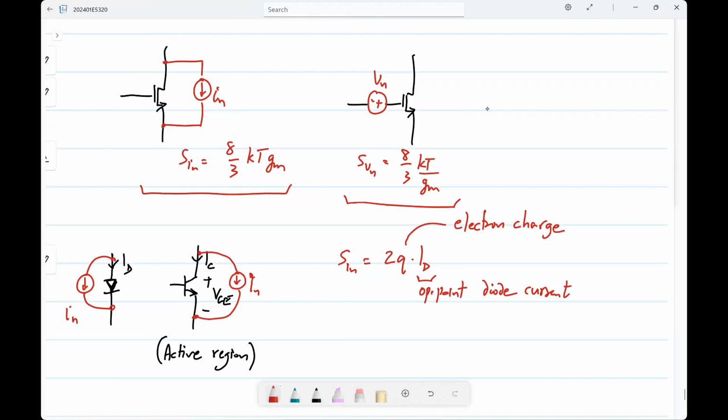In the small signal model of the MOS transistor, we have the current source going from drain to source, the drain current in the same direction, but it doesn't matter if you had put it the other way. The only thing is, in a single calculation, you don't flip the polarity in the middle, because you could be doing calculations for two different things.